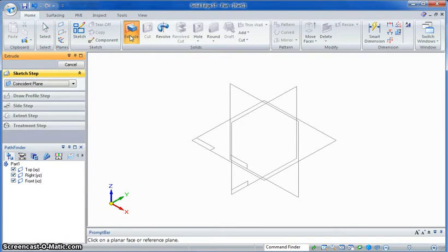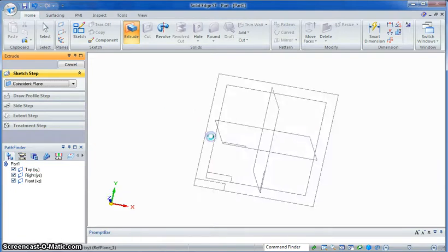the middle. The reason you can tell that it's the protrusion in the middle is the circles cut out in the middle. If you look at the top view, you can see the edge of those circles, which is indicated by those hidden detail lines, extend right to the top and bottom of that shape. So those hidden detail lines give us the information to tell us that the middle piece is sitting up from a base plate. Okay, so we're going to start with the base plate.